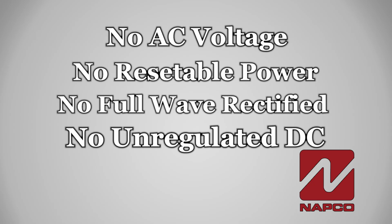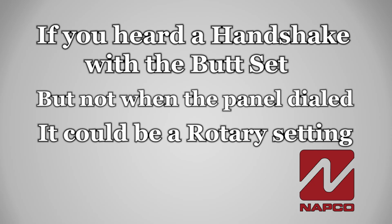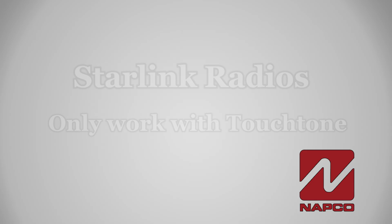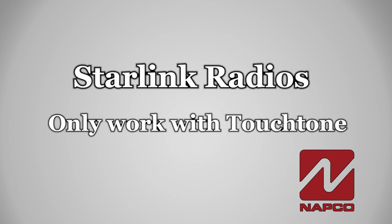If the power is correct and you're still not getting a handshake, there may be something wrong with your radio. However, if you heard a handshake when you dialed with your butt set, but not when your panel dialed, it could be caused by a rotary dialing setting. For example, this is what rotary sounds like. If you hear rotary, that will not work with the Starlink radio. You can use touch tone dialing only.